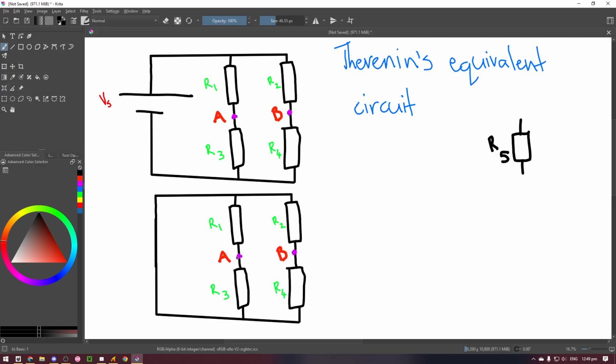The possible paths for current to flow from A to B are up or down through either of these resistors, and then once they're out here or here, which we can see is electrically the same point, it can then move through R2 or through R4, and then to B. This can be rewritten as 2 sets of parallel resistors in series, like this.